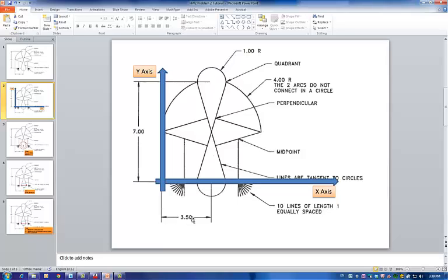As you can see here, 3.50, that would be the coordinate for my circle that I would draw here. And I will create another circle which will be on 3.57, and then the radius 1, the same as the other one. And then I will use the quadrant option to create these two lines. But first I will show you how to trim.